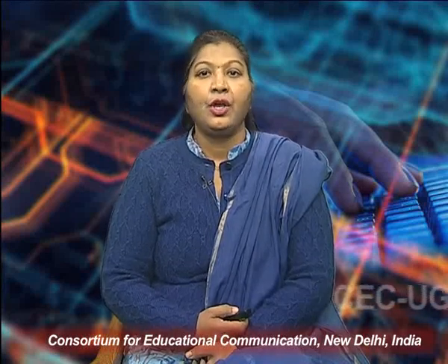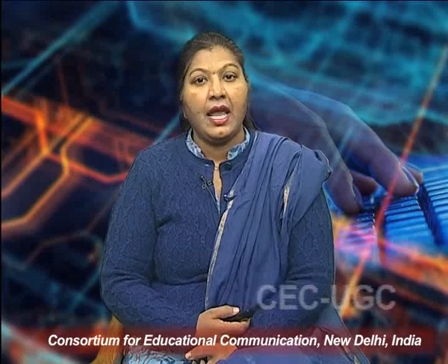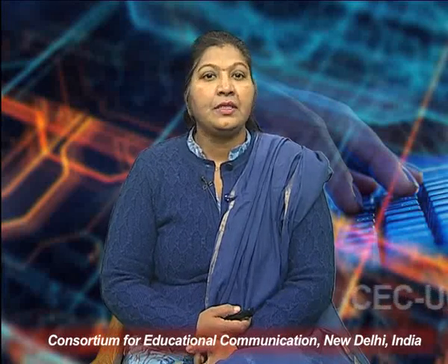A transducer uses a sensor and a signal controlling unit to perform the conversion. The sensor senses any change in the physical quantity or the energy and provides a non-electrical output. It can then be converted into a proportional electrical signal by using the signal controlling unit. It means a transducer uses two parts. First is a sensor which converts one physical quantity into another, but not into an electrical output, and by using the signal controlling unit we convert it into an electrical signal.